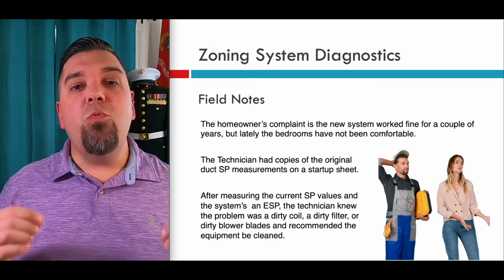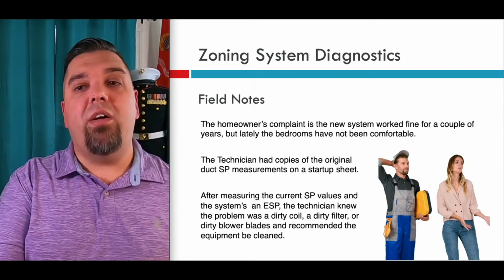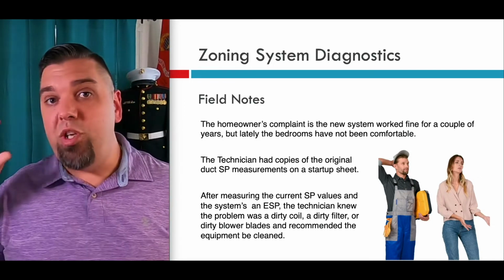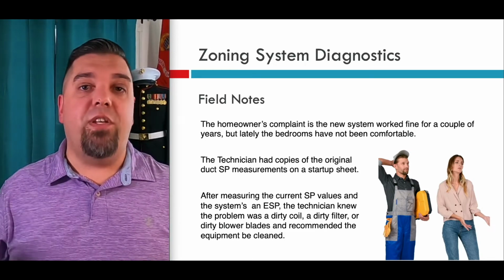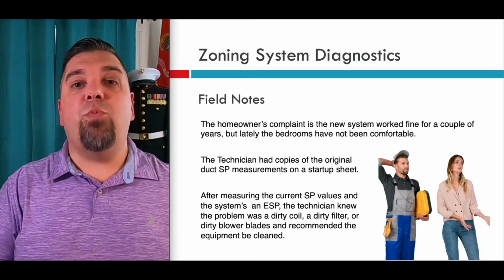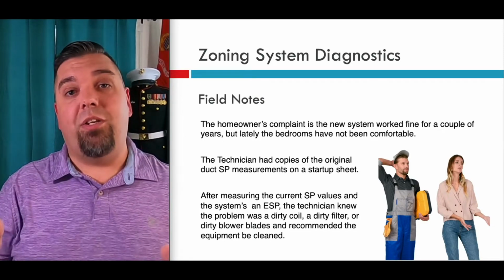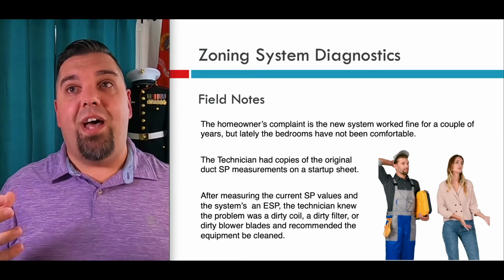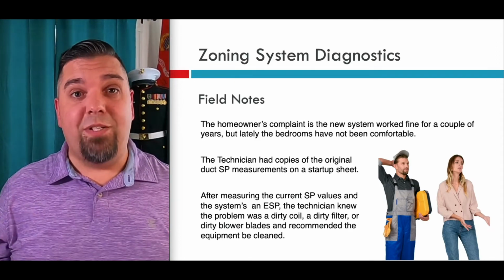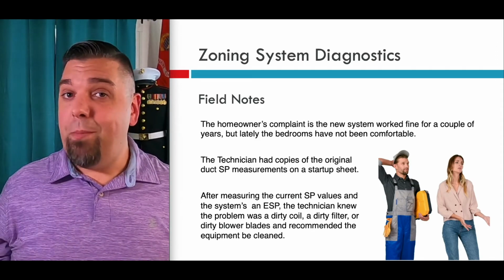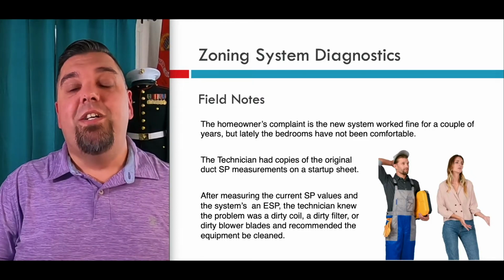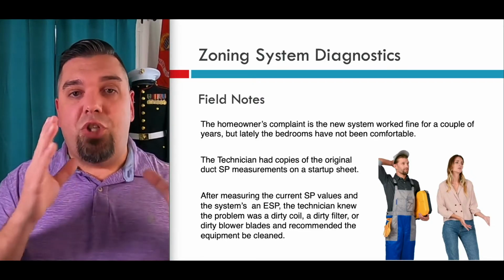So if you measure, it tells you a lot of things that down the road when you remeasure it, how far off it is from design, right? And that's when you start to have to, let's say, cut into plenums to clean coils, right? You don't want to do that not knowing, because it's time consuming, and if that doesn't fix the problem, you're probably not getting paid for that labor, okay? So very, very important. Document this stuff.